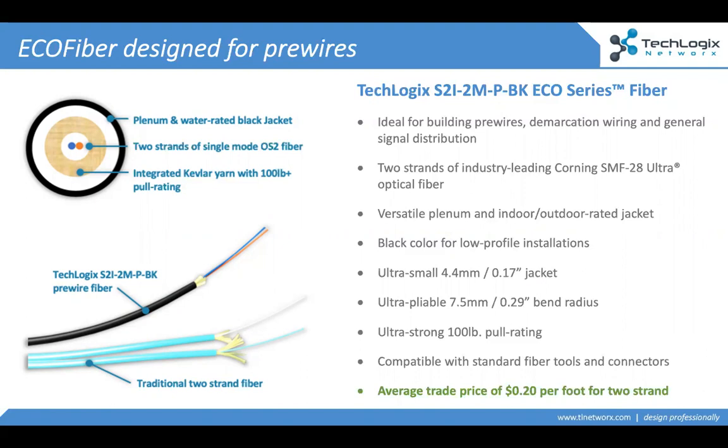There are electronics. We'll talk about that here in a minute. And that is actually one of the big drivers of this category. The fact that you have things to plug into the fiber now. The fact that you can integrate your fiber with twisted pair, like security cameras that have an RJ45 port, things like that. We'll talk about all that here in a minute. But most fiber, honestly, based on the price, based on how it's built, is being pulled dark, meaning it is being pre-wired. It is not even being terminated. It is being pulled for future expansion, future bandwidth, future video resolutions, okay? And the most popular fiber that you are now seeing in AV projects is single mode.